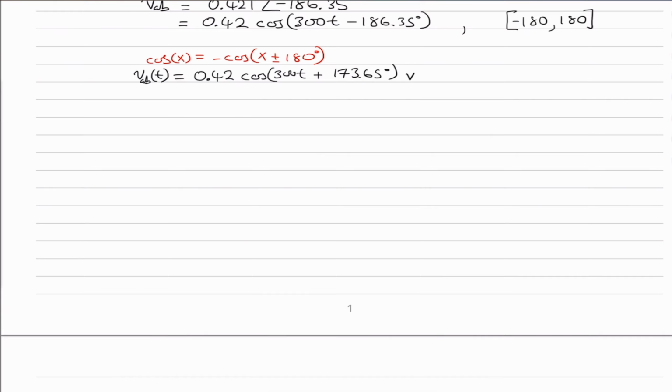By doing that, the current I of S is coming into the node. So we have a minus, and when we use the node voltage method, we're basically taking KCL at that node. It's just like a current equation. So minus the phasor counterpart of IS of t, plus V divided by our impedance for our resistor.